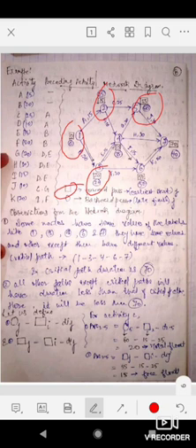Come here to node 2, where 15 is written inside the square. What does 15 represent? We can start activity C only after 15 days, because activity A will take 15 days for its completion.